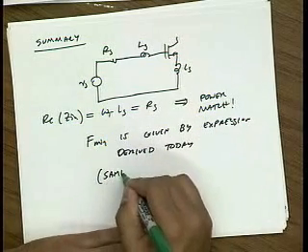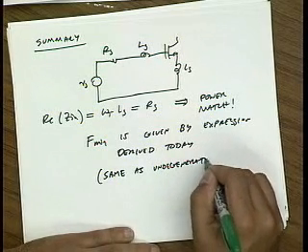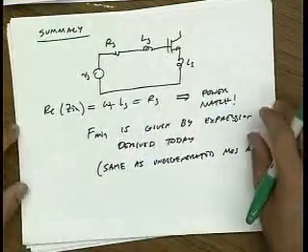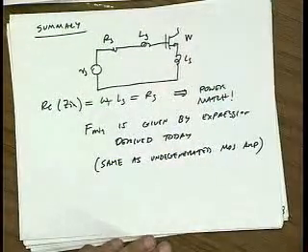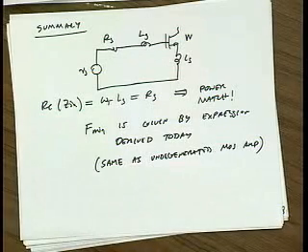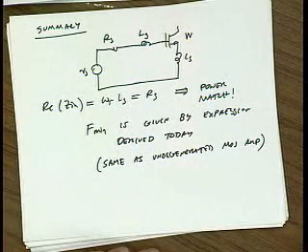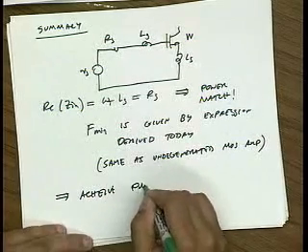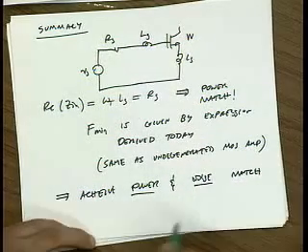The important point is it's the same as the undegenerated MOS amplifier. And so it turns out that if you're willing to sweep things, you can play around with your device size and find the device size such that the optimum noise figure source resistance is also the same as the power match. So this allows you to achieve a power and a noise match. Okay?